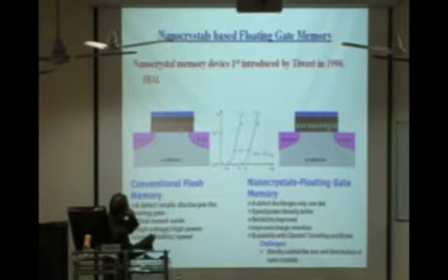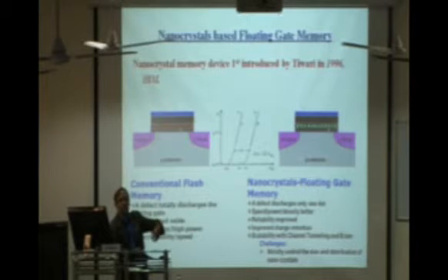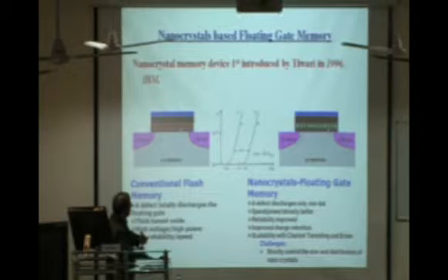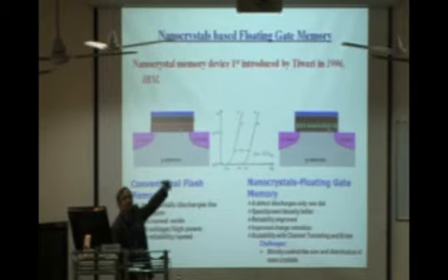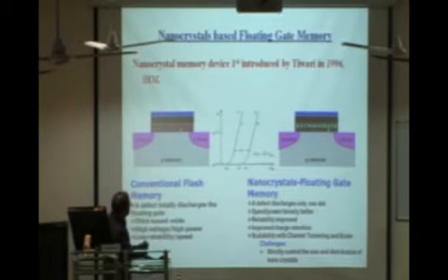Now, if you put these quantum dots or nanocrystals inside these MOS gate oxides, they can trap the charges. So if they trap the electrons, next time you have to apply a much larger voltage, because these dots are charged, so they will basically screen the potential that you are applying to the gate. So you have to apply more potential to switch on the device. So this can be used as either one of them can be 0. That means you want a high threshold voltage and a low threshold voltage.